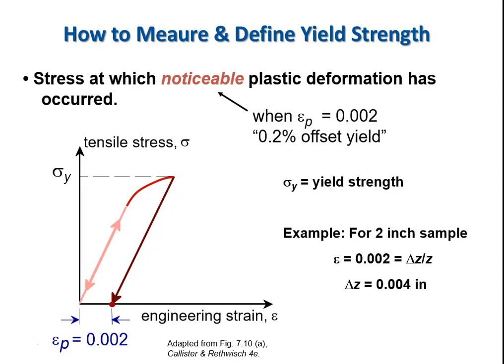This is not used for every material, but it's fairly general. It's included in a lot of the ASTM tests for metals and more rigid polymer uniaxial tensile tests. If you see a specification noting a yield stress or a yield strain, if it's not otherwise noted, chances are it's referring to the 0.2% offset.